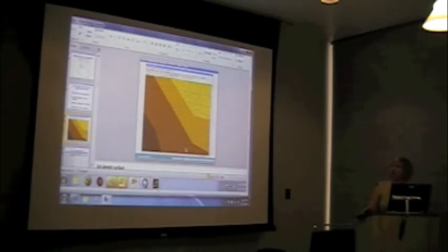You could, well, usually you have to consider a few conflicting requirements because you want people in a zone for transportation to be similar age group, similar income group, and if you want to model transit or pedestrian or walkability, then you have to try to get people who are likely to walk in one zone, people who don't want to walk in another zone, and sometimes it's hard.